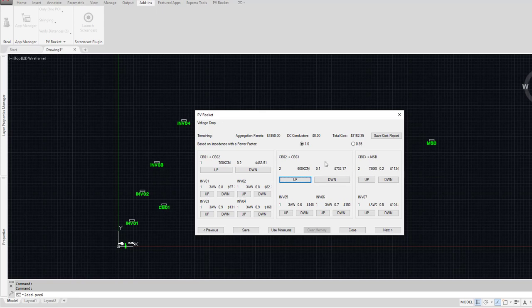This is for these segments only because those are for the main switch, for the main aggregation panels. But when you get down to the inverter, it's accumulative along its route. And that's why we have cost associated here, because it might be cheaper to move one of these up, or it might be cheaper to move one of these up and make 3 come into compliance down here, if that makes sense. We're getting some cutoff just a little bit that I hadn't noticed before, and we'll get that worked out. This one might be cut off because there's only one inverter.